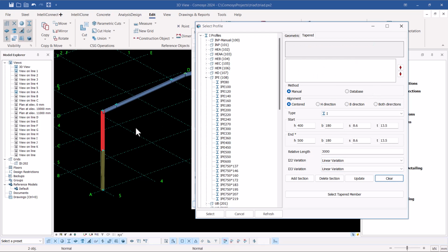So once you're here, and we've clicked on this, we've picked on the final section of the column. So remember, the top end for the bottom one, the top end here was 500, the bottom was 400. So let's switch back and change the same thing here. This will be 500, beginning from there where the bottom ended. So I'm feeding here 500, and at the top this will taper at that height of 600, which is end. I'll just key in there. So the rest I'll just retain them as they are.